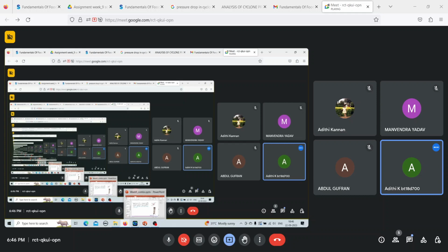So this is basically the centrifugal acceleration that is given as 10,000 into G. The centrifugal acceleration can also be given as omega square r. Now if you multiply that by mass, you will get centrifugal force. If you remember, the centrifugal force is m omega square into r, where the acceleration is given by omega square into r.